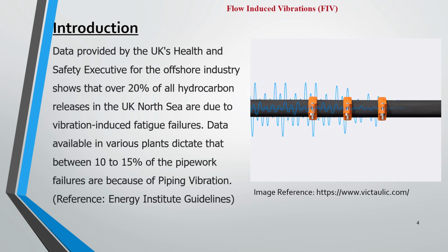Now data provided by the UK's Health and Safety Executive for the offshore industry shows that over 20% of all hydrocarbon releases in the UK North Sea are due to vibration-induced fatigue failures. So you can find that a major cause of failures in any operating plant is piping vibration.